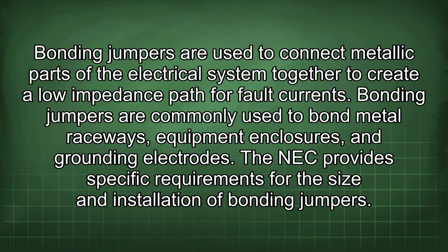Bonding jumpers are used to connect metallic parts of the electrical system together to create a low impedance path for fault currents. Bonding jumpers are commonly used to bond metal raceways, equipment enclosures, and grounding electrodes. The NEC provides specific requirements for the size and installation of bonding jumpers.